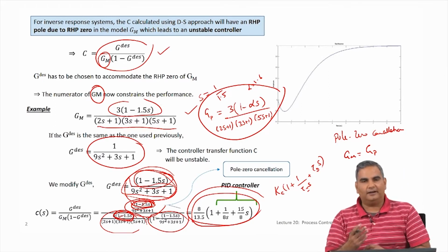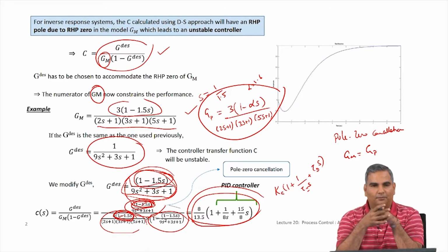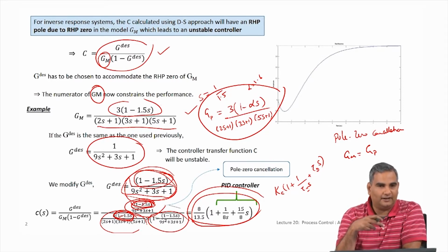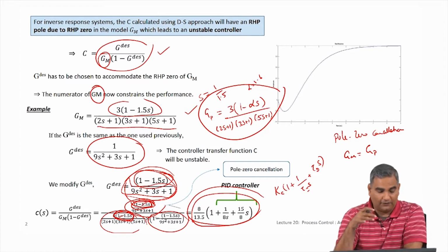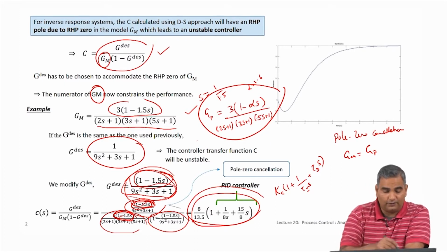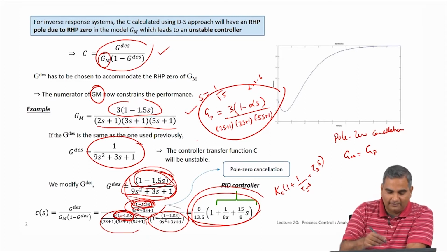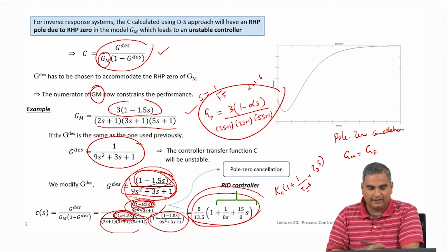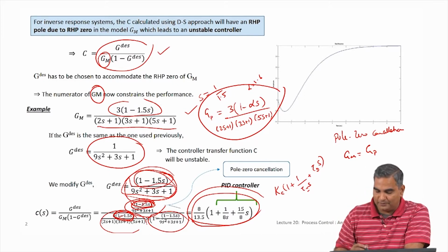That will be realistic: you go to a plant, you have a concept of a model and then use that model to design a controller, but when you finally test the controller, it is being tested in a real plant where the process could be different from the model. In fact, the process could be grossly different from the model, then you will have more difficulties, but if it maintains the same structure, and let us say only this changes, then we could ask what happens to the performance. What will happen to the performance is interesting.